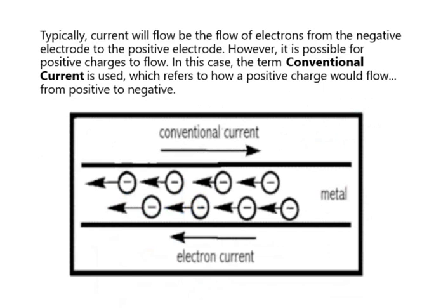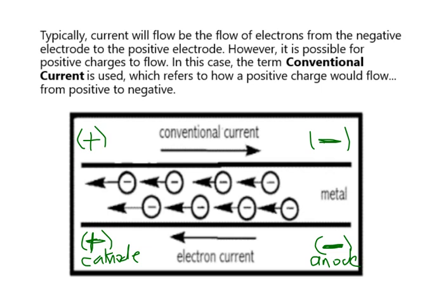And then the second slide here just talks about what I've already mentioned before. Electrical current, if I talk about electron flow, that's what actually moves. Electrical current always goes from the negative pole to the positive pole. That's what electrons do. Any of you guys in Chem 30 currently? You doing redox and cells yet? Okay, so you're going to come across this. This would be your anode to your cathode, in your battery type stuff. Electrons go anode to cathode. However, conventional current, based on Ben Franklin's horrible mistake, actually goes from positive to negative. So if you ever describe conventional current, it goes the other way, which is annoying.